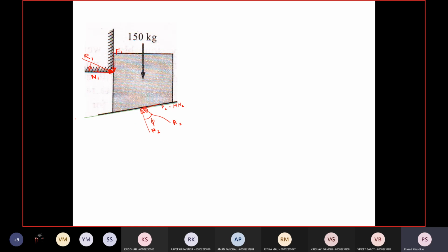And the angle of this wedge is given as 10 degrees. So angle of the wedge is 10 degrees. Right. So if I draw a vertical line, the normal will also make an angle of 10 degrees. I hope you are well versed with this technique of marking the angle. And so now let's see the finished free body diagram.